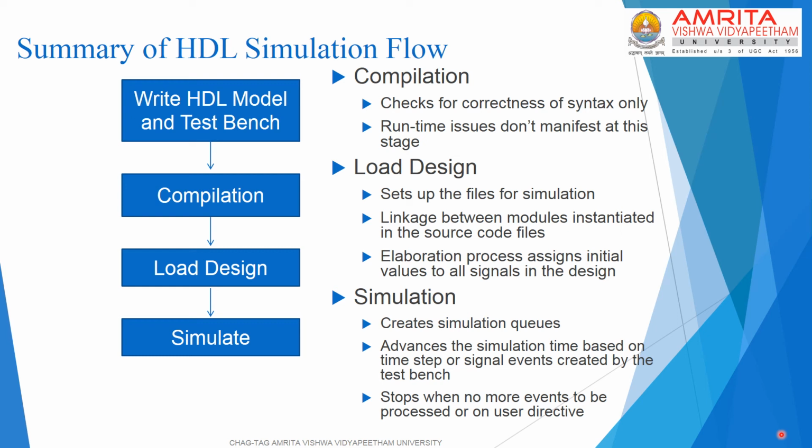Likewise, in HDL simulation, the linkage between different modules that are instantiated in a particular file will be verified during the load design phase. Another step that is executed in this phase is called elaboration, where the initial values of all the signals used in the design are assigned.